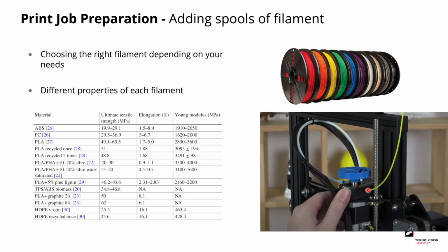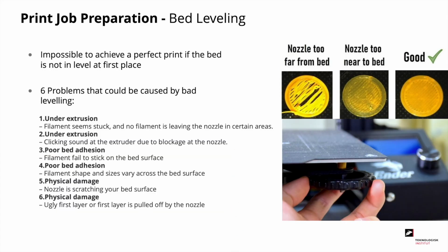Finally, you need to be aware that there are different properties for different filaments. The final step before printing is bed leveling. You have to have a level print bed to be able to print good first layers.